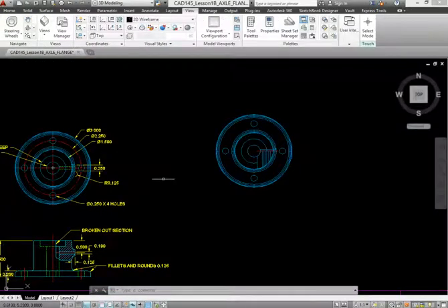Okay, now that we've got all the parts drawn for this three-dimensional object, we need to rotate it into a view in which we can see our three-dimensional object on our title block. We're going to use a command called rotate 3D in combination with using these commands here for the UCS icon. Right now the UCS is pointing in the direction we just moved it, which is currently on this axis here. Let me demonstrate that again.